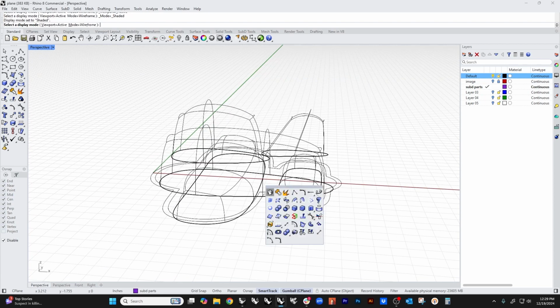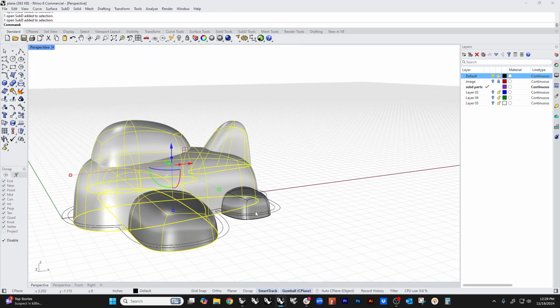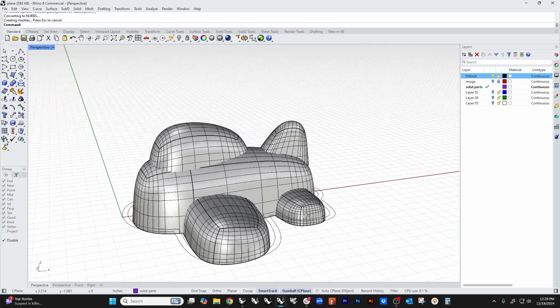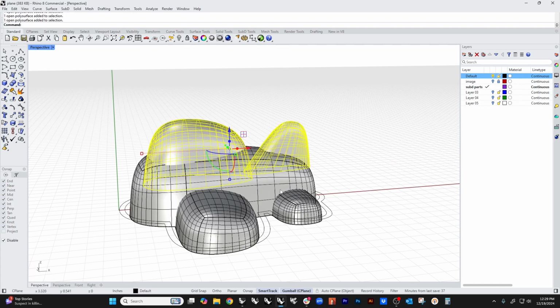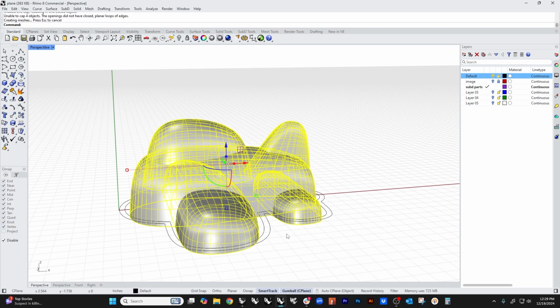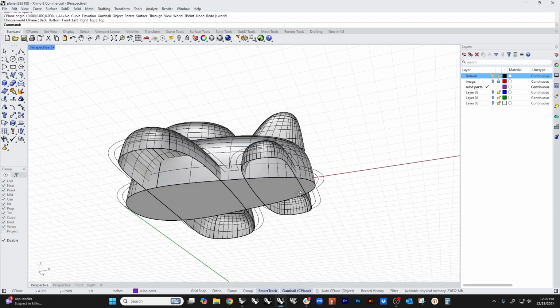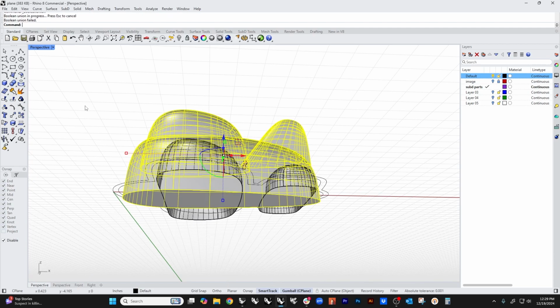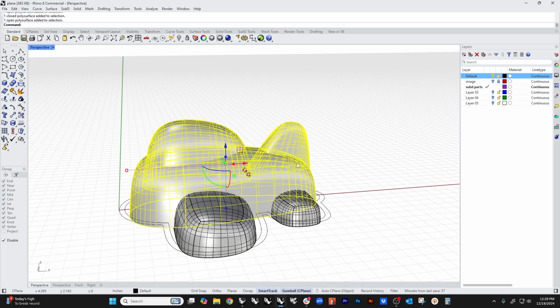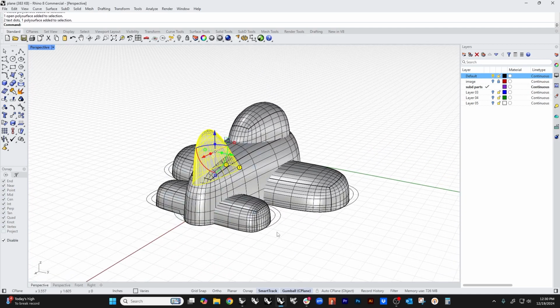I'm going to go and we'll do two NURBs again, like we did before. Let's spell it right. And I can delete the input, that's fine. And we've got, once again, our completed part. Now, if I grab all of these things and cap them, it should close them up. And if it doesn't, looks like it capped that one. Let's Boolean those together. And it looks like the Boolean failed. So let's figure out why.